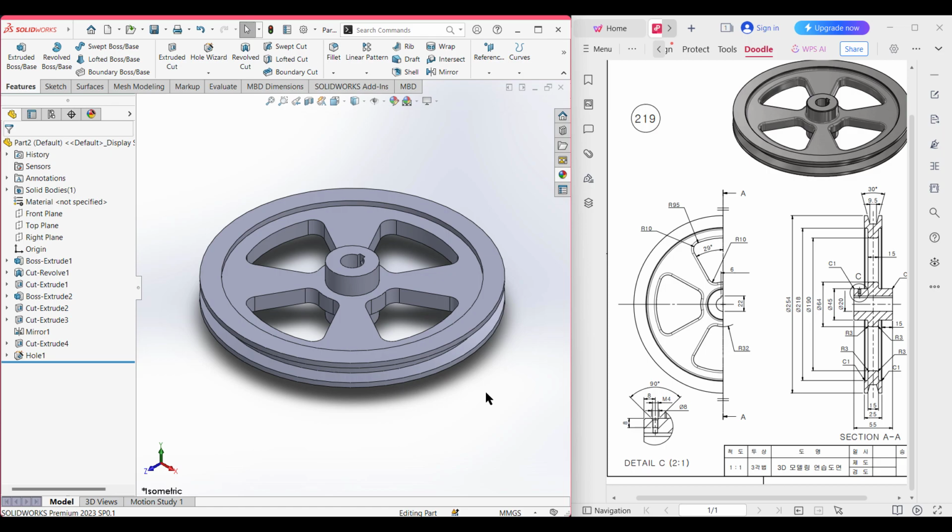In our next portion, this time we'll talk about all the fillets and chamfers. If I go back to our sketch, we can see this portion, all the extruded parts have a fillet of radius 3 unit here, and this other side also has a radius 3 unit fillet. Then if we look here, here and here, we can see that we have a chamfer of 1 unit, so we'll give a chamfer of 1 unit.